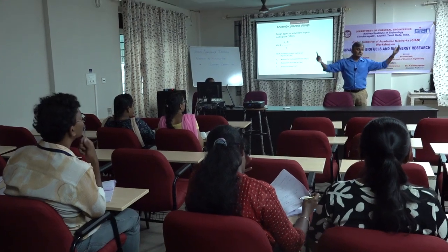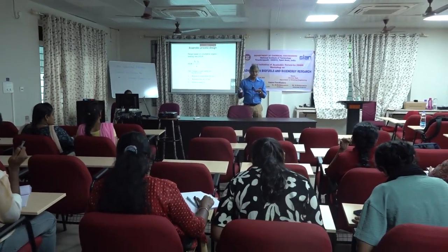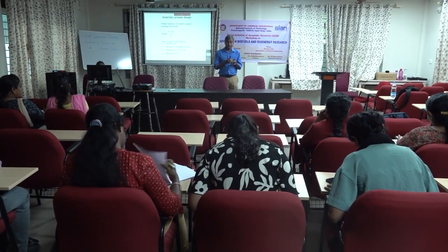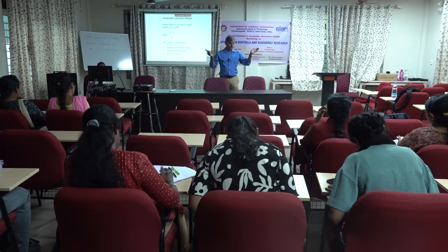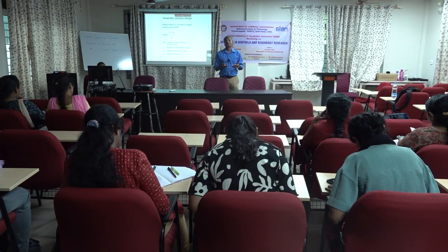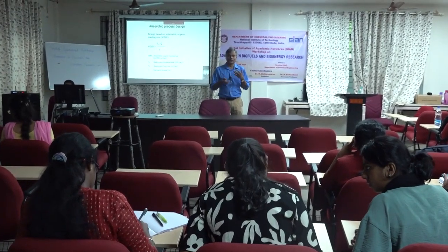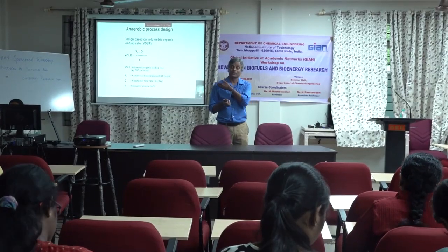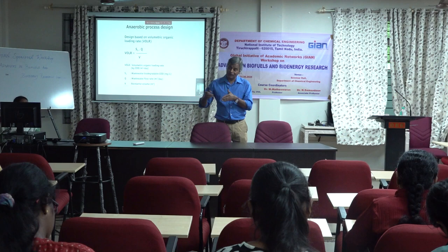See? Exactly. That's how you calculate it. It's simple. If you know the concentration of your COD in your waste stream, if you know your flow rate, if you know your reactor size, you can calculate how much organic loading you want to feed them. So that means with 7,000 milligram COD in there, you calculate the loading rate, and that's how much should go per day into your bioreactor.